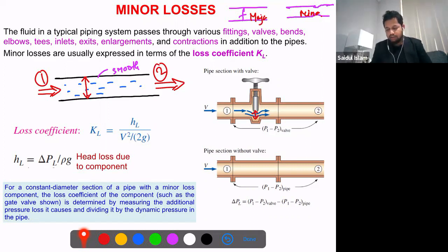So it is very clear that major loss is significant. Yes, some of you said no, but it could be. The minor loss could be significant. It could be higher than major loss in some cases. When you have a large or long piping system, then the minor loss is negligible. But if you have a couple of these inserts in a very short distance, let's say this is the valve, and now you have another valve here. So we can say this valve is from this way.